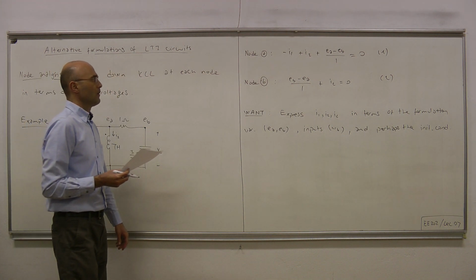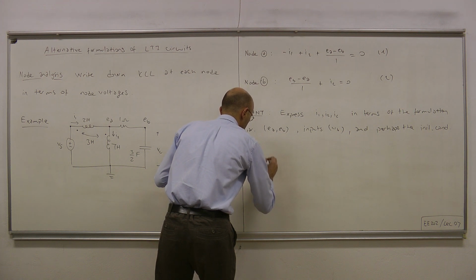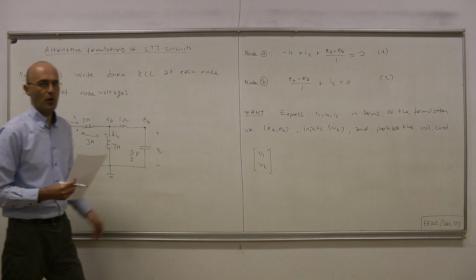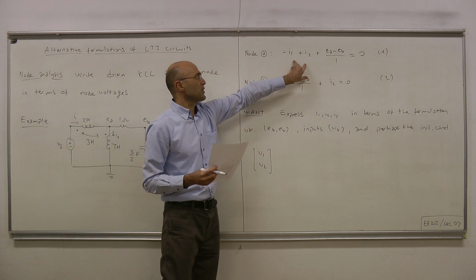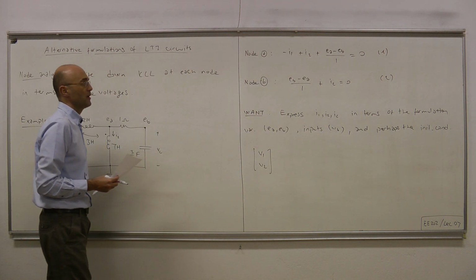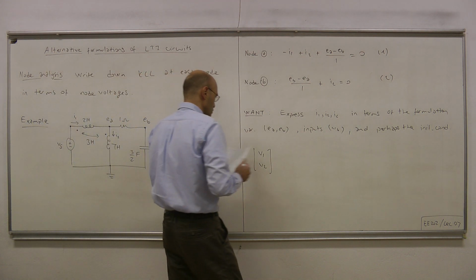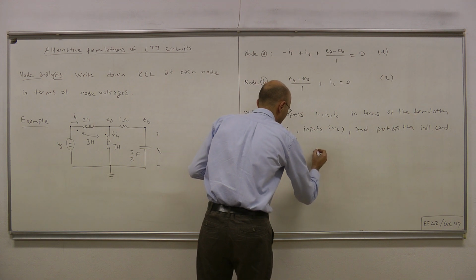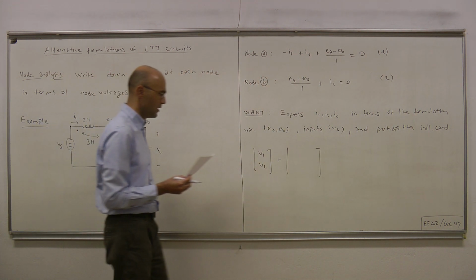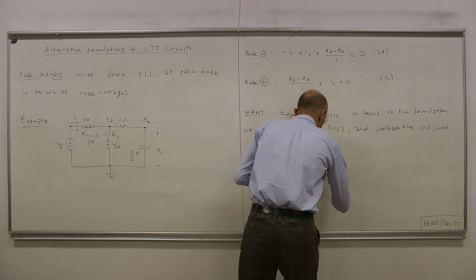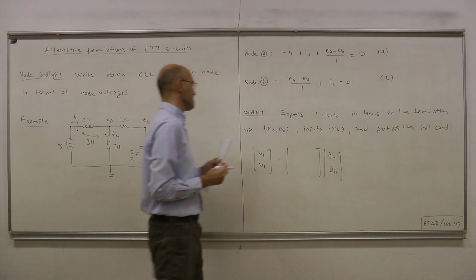Okay, so let's therefore use the terminal equations for our dynamic components in order to express I1, I2, and IC in terms of our formulation variables. V1, V2 equals L, being our inductance matrix, times the rate of change of the currents, dI1, dI2.